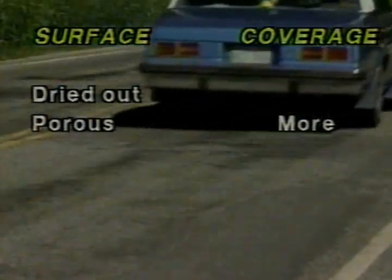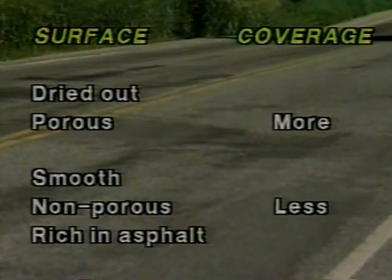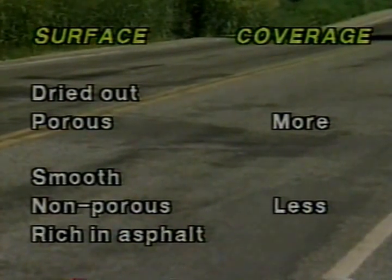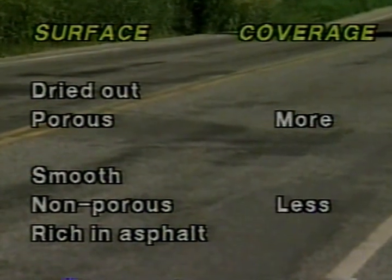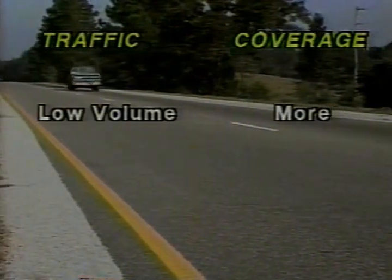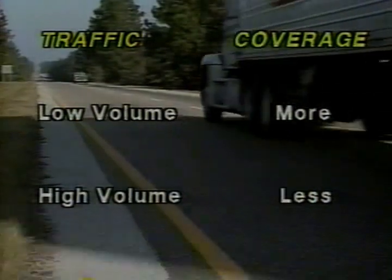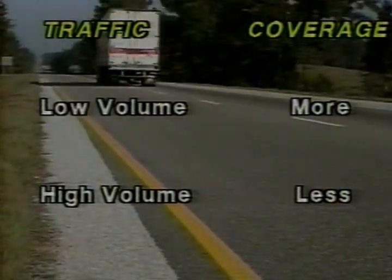The general rules are, for dried out and porous surfaces, more oil should be applied. For surfaces that are smooth, non-porous, and rich in asphalt, less oil should be applied. In terms of traffic, for lower volumes, a little more oil should be applied. But for higher volumes, a little less oil should be used.